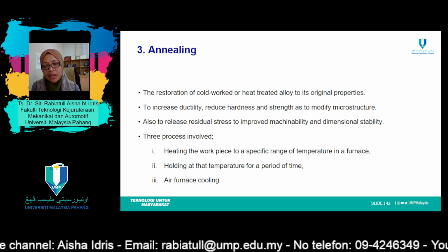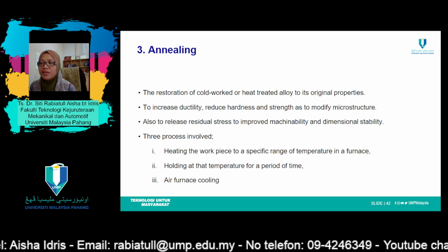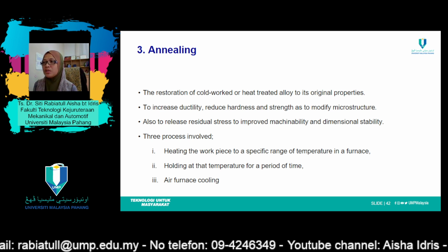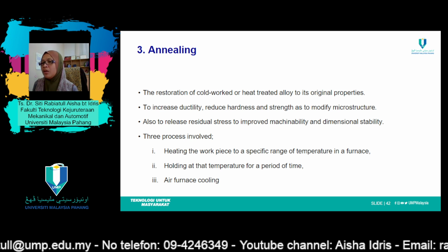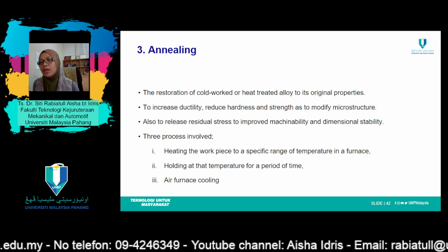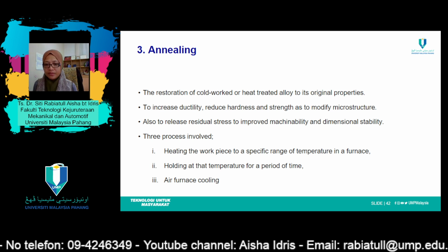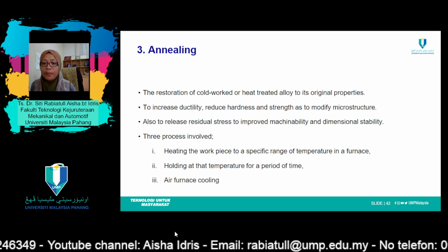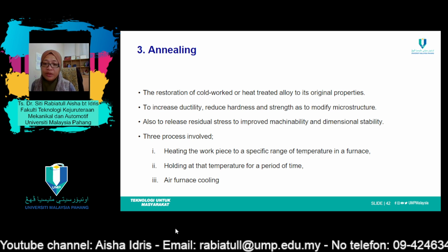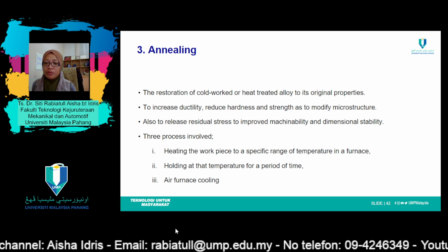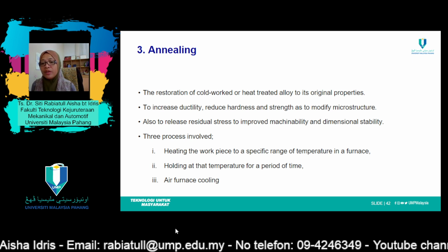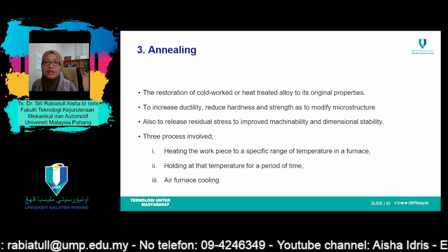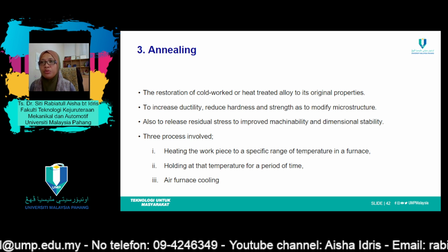Same thing for steel. After certain work or being heat treated, it will feel stress. So to reduce that stress and regain its original properties, we introduce the annealing process. Three processes are involved in annealing: heating the workpiece to a specific range of temperature in a furnace, holding that temperature for a certain period, and after that, furnace cooling. Put it in the furnace to slowly cool down, I mean, let it cool together with the furnace.